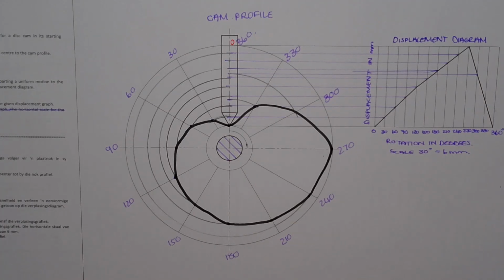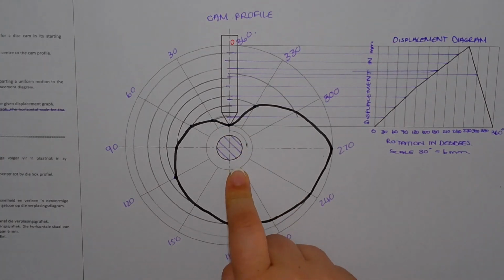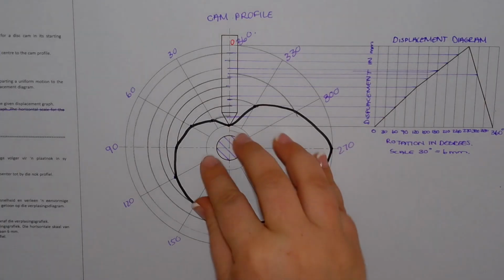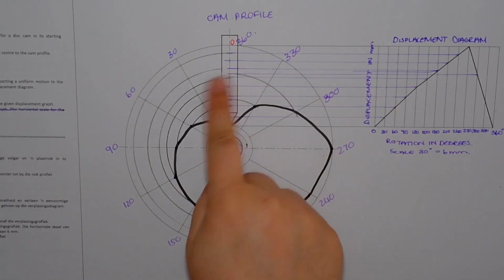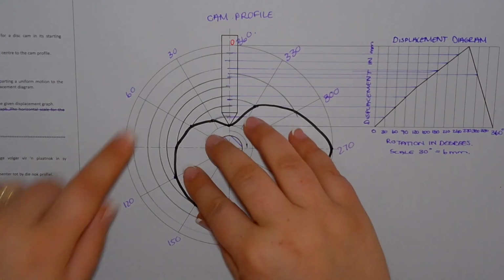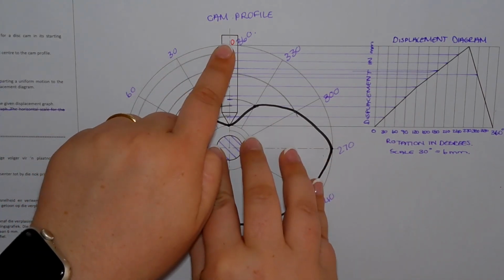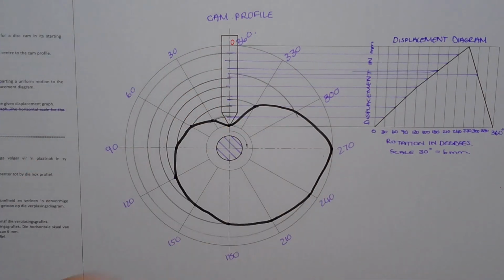The reason for labeling anti-clockwise, if it says clockwise, is because as this thing turns, let's say this thing moves and not the follower, then turning clockwise would mean 30 would meet it first, then 60. So it's actually in the correct order. It just looks like it's backwards because of how it will turn.